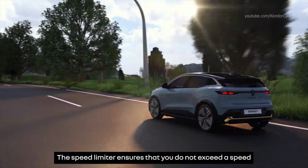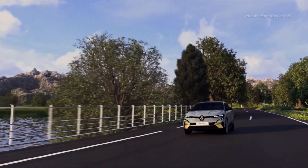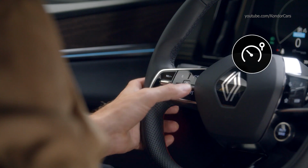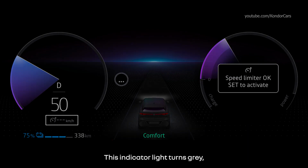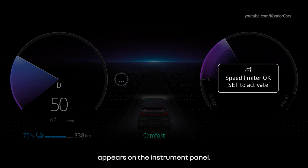The speed limiter ensures that you do not exceed a speed that you've set previously. Press this switch to turn the feature on. This indicator light turns grey, along with dashes to indicate that the speed limiter is on and ready to store a speed limit, and the message "Limiter ready, set to activate" appears on the instrument panel.